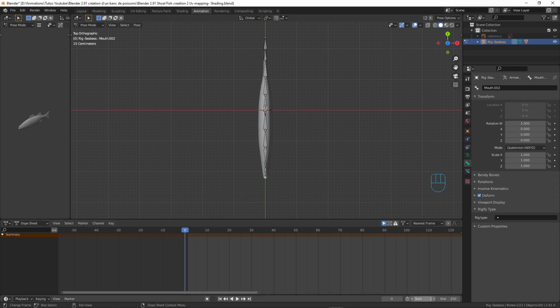and we will start from 0. So start at 0, and as we know that the entire cycle will take 20 frames, the frame 0 and the frame 20 will always be the same. It has to be the same. And so the key that I put on frame 0 has to be exactly the same on frame 20. And like that, I will just finish my animation at 19.